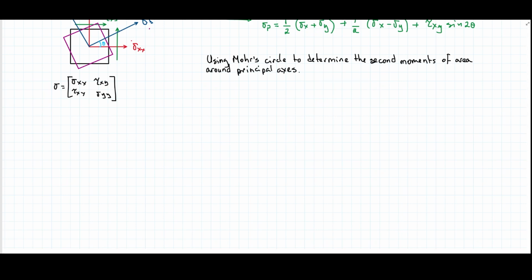So I'm going to bring a Cartesian coordinate system, and on the way to use the Mohr circle to determine the value of those inertia properties in the principal axis system, or Cartesian coordinate system formed by the principal axis, is saying, okay, this is something that is going to represent in here your second moments of area, or moments of inertia, both, and this one is going to represent your product of inertia, xy.